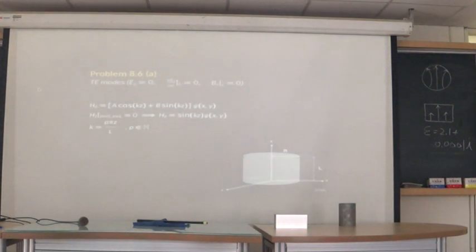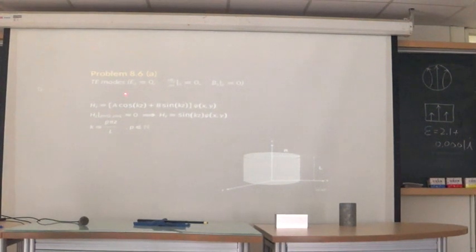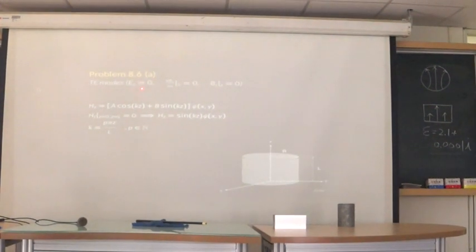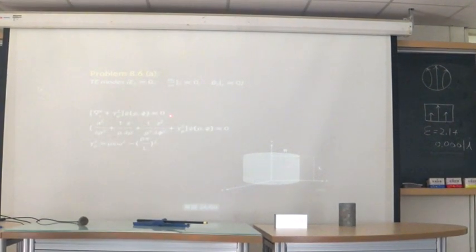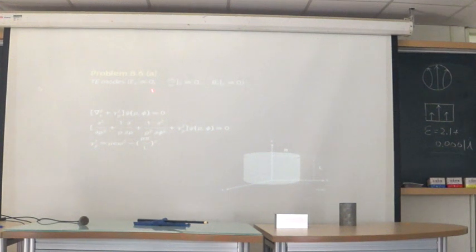And the same thing is for the TE modes. The calculation is similar, but because this is the TE mode, instead of calculating the electric field, we use the H fields. And again, we calculate the H fields and satisfy the boundary condition. We find that it should be assigned here. And again, we solve the Helmholtz equation in cylindrical coordinates and find the solution should be a Bessel function.